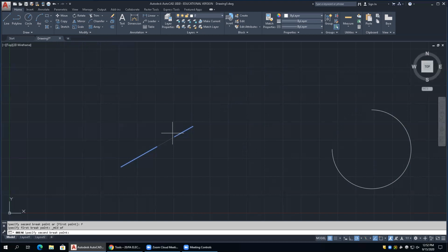The @ symbol in AutoCAD means the first point. So if you just hit the @ symbol, which is shift number 2, you get the @ symbol and then hit enter, it'll do that for you. So you don't have to do another O-snap, grab it and select. So you could do exact snapping, or you can just type in the @ and you did it.